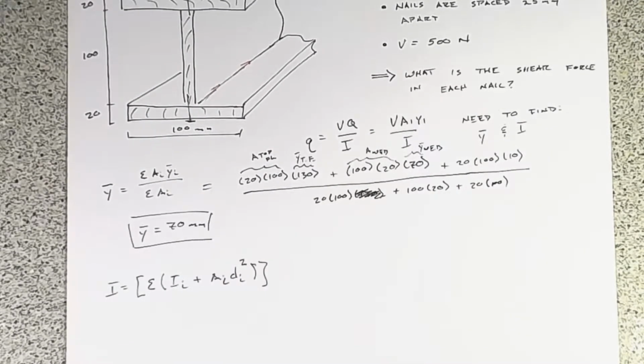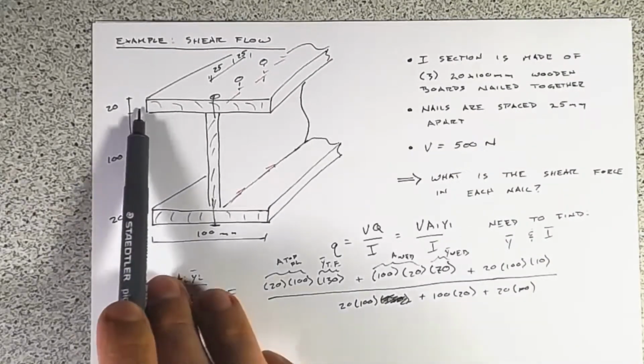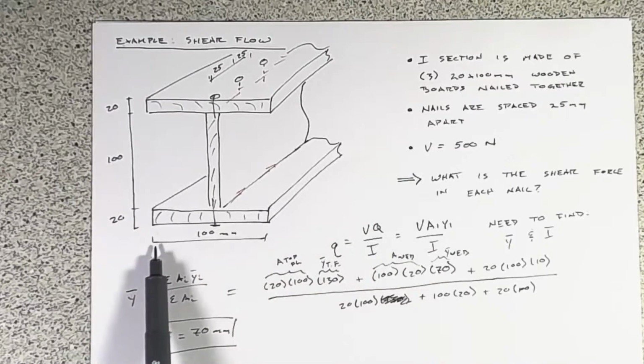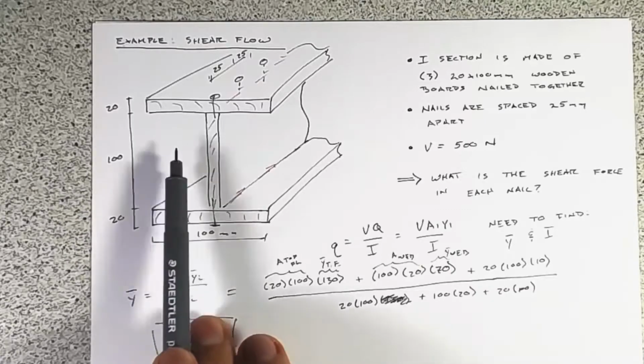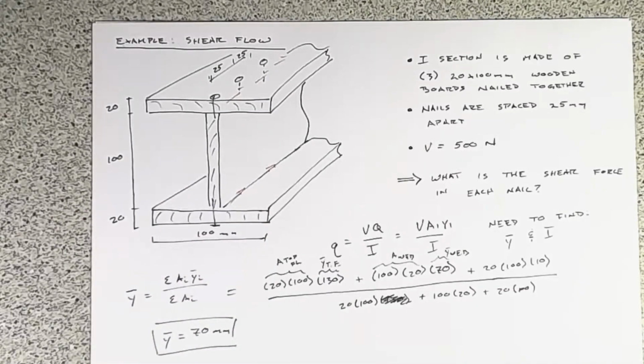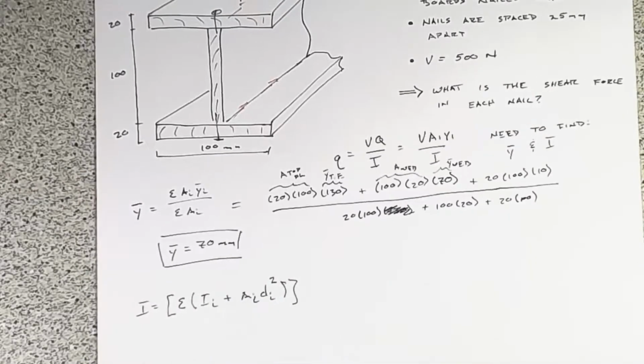If we work all of that, I'm going to use three pieces essentially. I'm going to find the moment of inertia of the exterior of this box, and then subtract out the two voids on either side of the web. I'm doing that because all of those pieces have their centroid at the same location, at 70 millimeters from the middle, and so this d squared portion becomes 0.